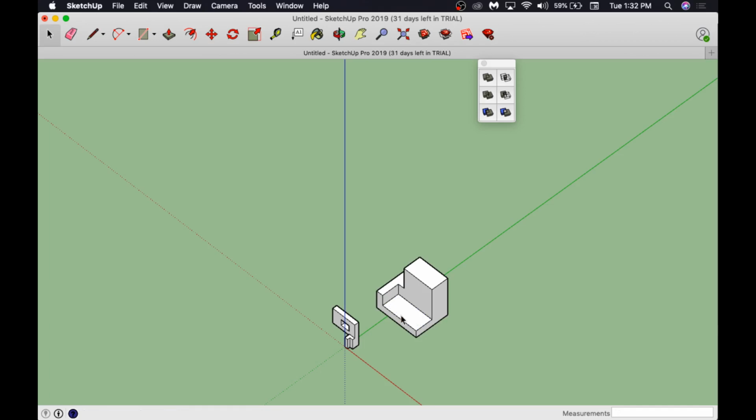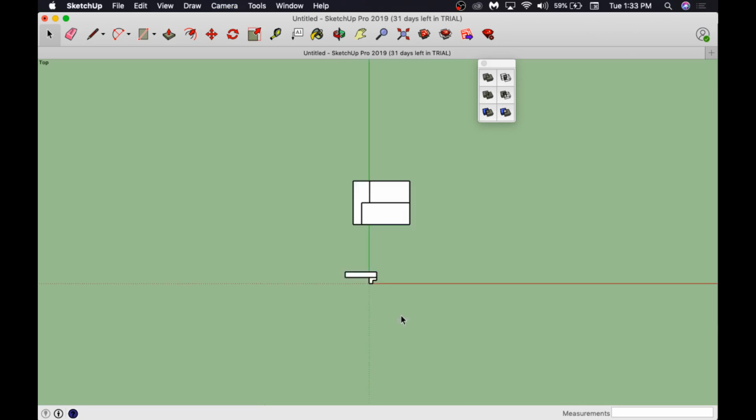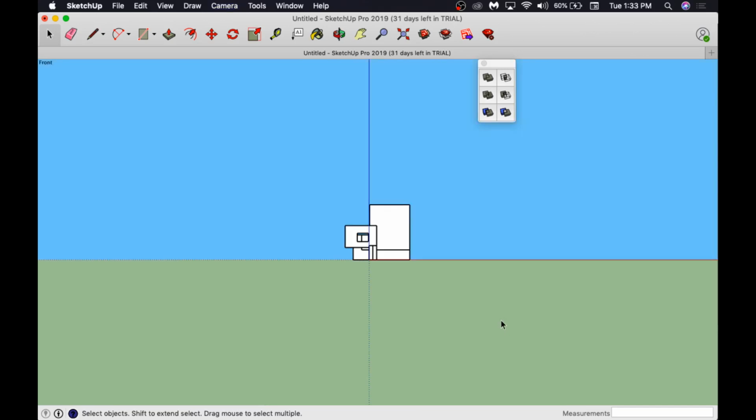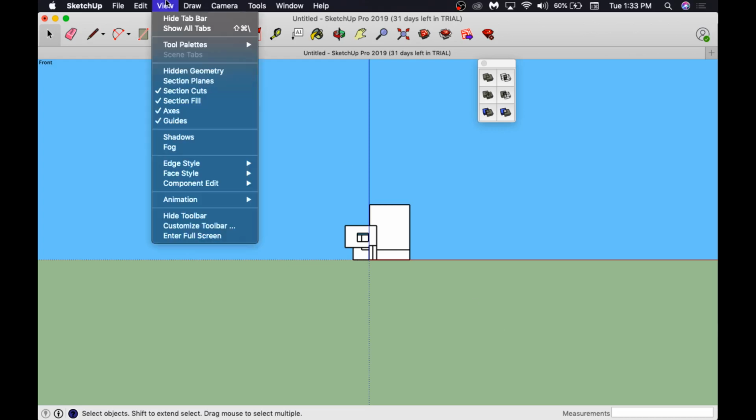So generally we use, and this is a great question, orthographic views, and just make this a rule of thumb. We use orthographic views: plans, sections, elevations, and isometric. Plan drawings are flat from the top view. So Control 1, plan views. Control 3, elevation views. And then obviously a section, which is the way we push into this object. And then the last one will be the isometric view.